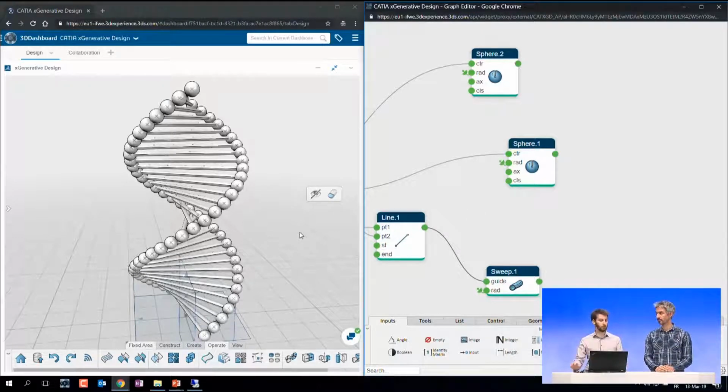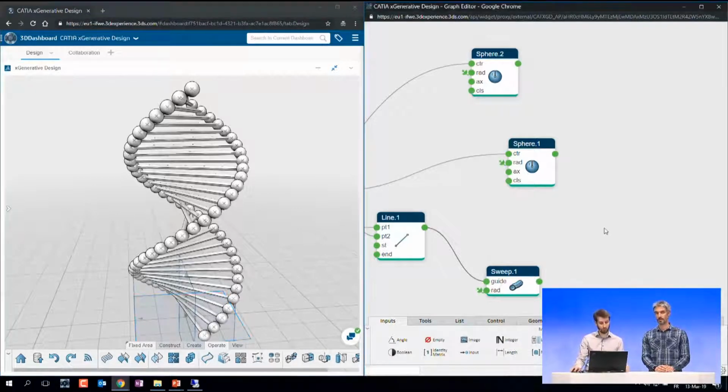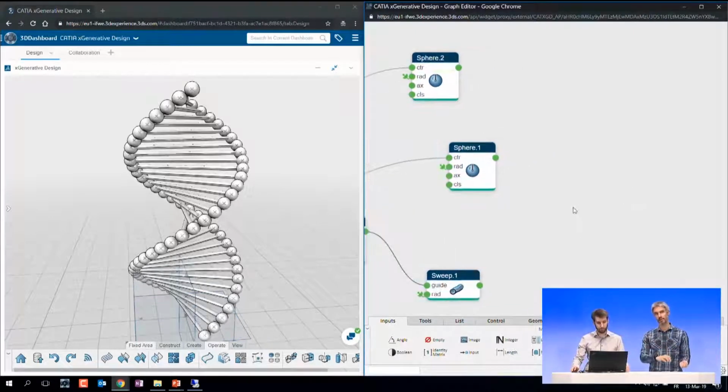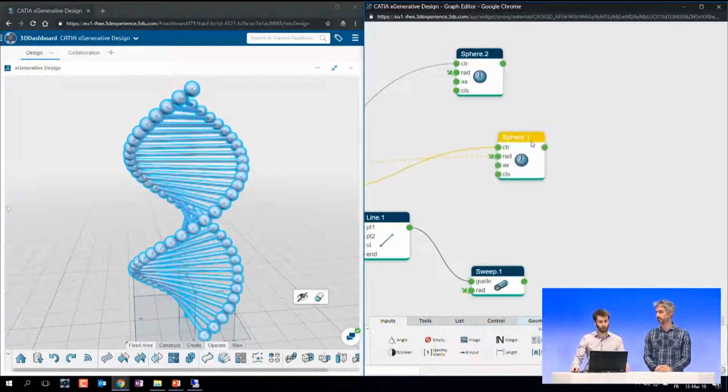When I create again a feature through the interactive window, it will add a box, and it's the same story. If I add a box, it will add it in the spec tree. You can retrieve it through the interactive window. And you have a cross highlight, so if you select a box in the tree, it's highlighted in the 3D view. For example, like that, the sphere.